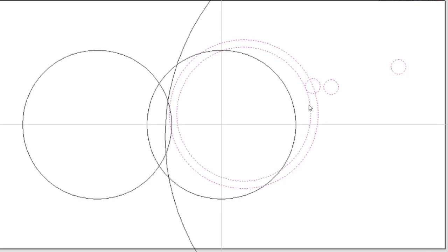So what we've covered so far is how to select objects. Number one is selecting each item: put your mouse over it and select it. If you want to select multiple items, one way is to hold the shift button down and keep putting your mouse over each item and select it. The other way is to create a box from left to right or right to left. Right to left will select anything the box touches. Left to right will select anything that's inside the box.